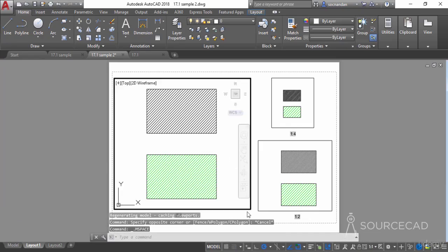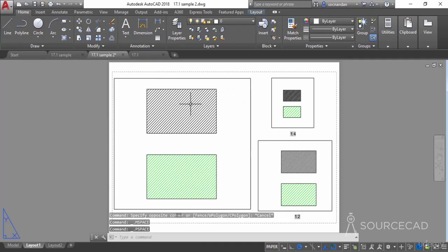Now in this scale, look at the hatch pattern. The spacing of hatches is equal in both of these cases. Now look at this hatch pattern. In this case, the scale is 1:2. As I am decreasing this scale, the gap of this normal hatch has also decreased. It has reduced to half of its original gap as it was in this 1:1 scale. So obviously this will follow properly here.